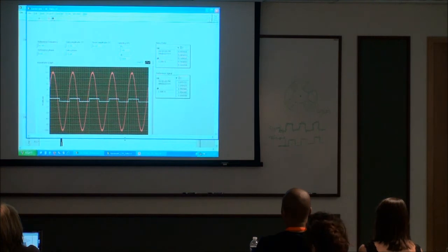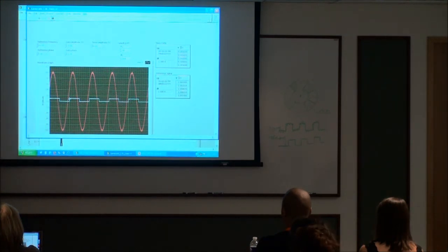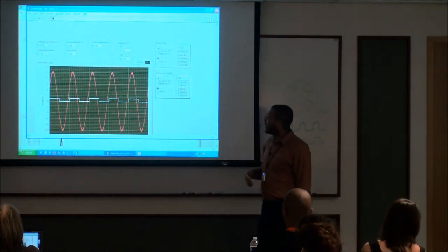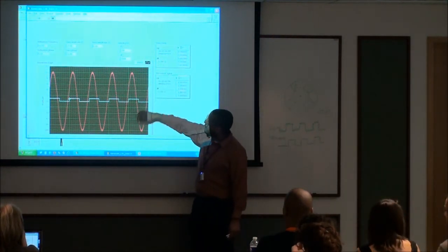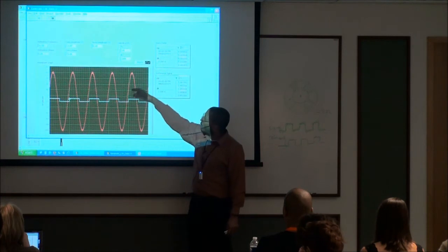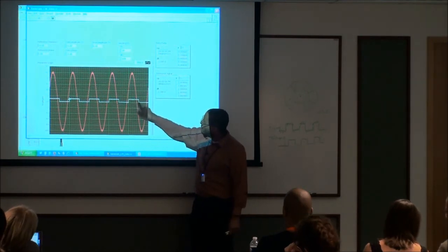So what the lock-in amplifier is going to do is, from the reference signal, figure out the frequency. The goal of this filtering algorithm is that I need to know the frequency and the phase of the reference signal, and then I'm going to synthesize a sine wave at that same frequency with that same phase, multiply it by the data signal, and use the fact that sines and cosines are orthonormal. I'm going to use the completeness of sines and cosines as basis functions, and express this sine wave as a sum of different sines and cosines at different frequencies. So I'm using Fourier analysis. What I want to figure out is the amplitude of this particular frequency sine wave that I generate based on the reference.